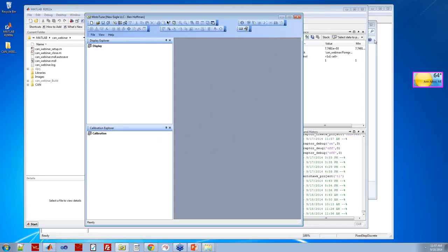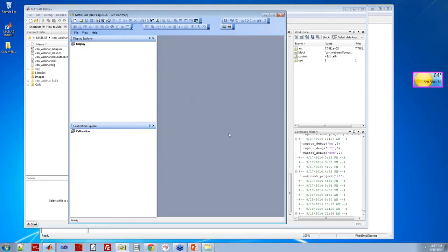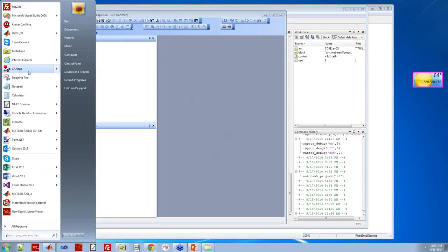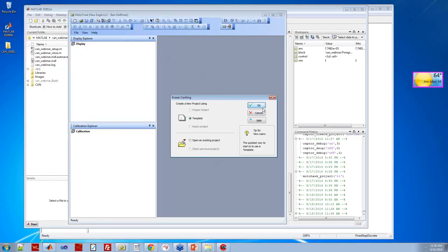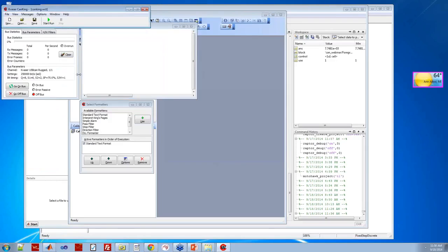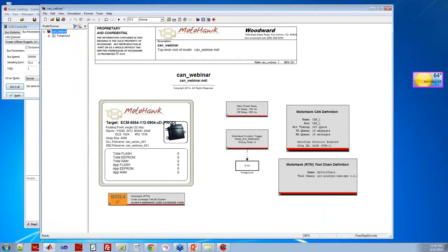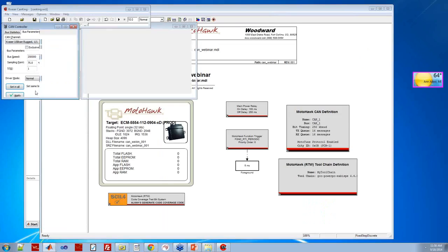Now, since we have a message that we're transmitting, I want to show the raw message, and a tool that we frequently use for CAN development is the Kvaser CAN King. So that allows me to go online. I'm at 250K baud, and you can see that I had defined that here in my CAN definition block.